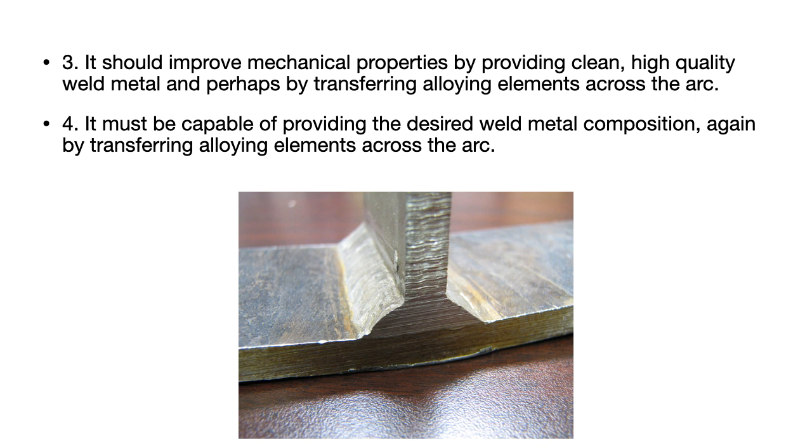They shall have a compatible composition. It can have different effects, not only in terms of mechanical properties, but also in terms of the corrosion properties. Say for example, you might have studied the electrochemical series. Each metal will have different electro potentials.